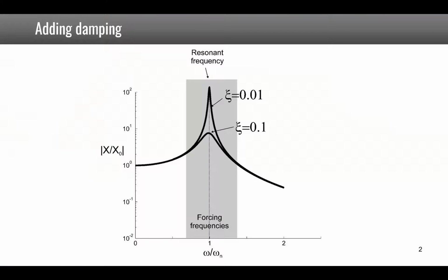When vibrations are excessive in a structure, a possibility is to dissipate this energy to lower the levels of vibration. And this is done by using damping. Adding damping, as we have seen in the video on 1 degree of freedom system, will be effective mainly around the resonance of the system. So basically the amplitude at resonance is limited by damping, and if you multiply the damping by a factor of 10, you will have an amplitude that is divided by 10.